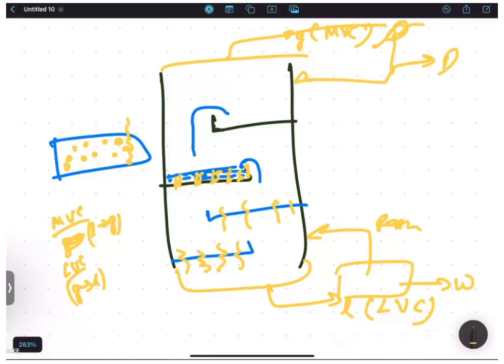Okay, and then again it will travel. So this time, the contact time, we take it as TC. Okay, this contact time, we take it as TC. And so for penetration theory, we say that the contact time for each of the bubbles is the same. Okay, like all the bubbles will have the same contact time. So that is the biggest assumption we have taken, and this assumption is not correct. All the bubbles cannot have the same contact time.